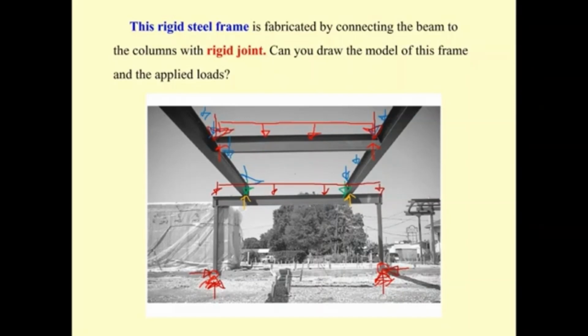They transfer all the forces into the reaction, the yellow one, and this reaction by Newton's third law changes to the green force. And since the beam of the frame has its own weight, it also applies force across the column and from the column to the support here. This is the kind of model that we use to model the frame and for the analysis of the frame.